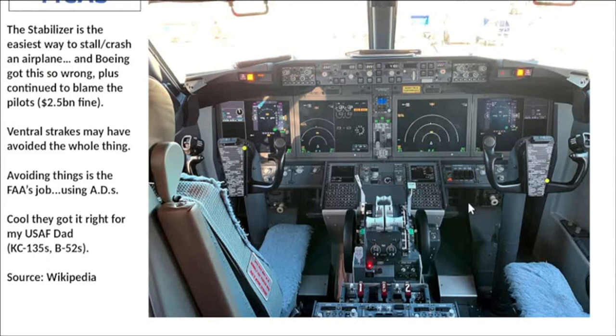So here is the cockpit of the MAX. It's gorgeous, and very big displays here too. It's amazing. On the captain's yoke, the trim button is on the left. On the co-pilot's yoke, it's on the right side. And this wheel here and this wheel here, these are the manual trim wheels. They have a white stripe on there, you just can't see it in here. But it's got a little handle that pops out, and you can rotate that wheel a lot of times if it'll still move. These switches right here are the switches that they wanted to be set to cut out.